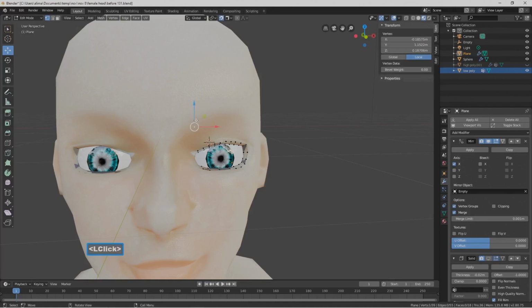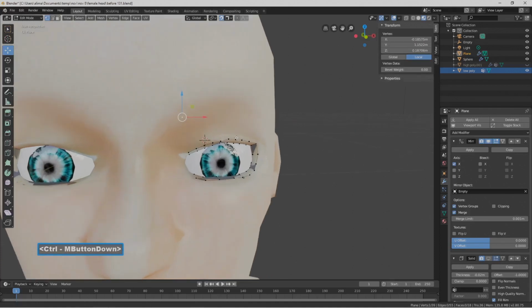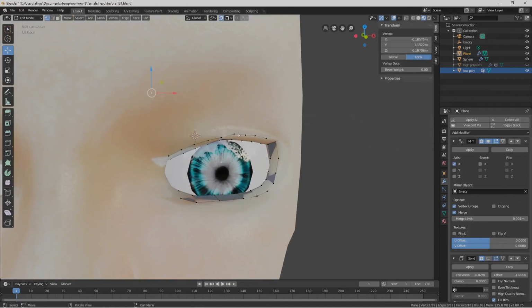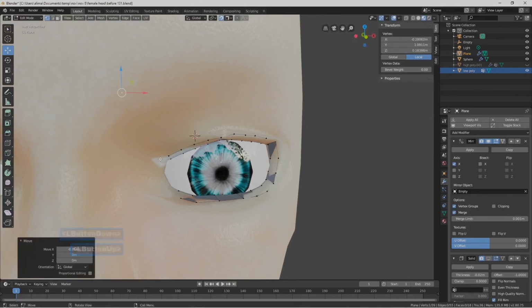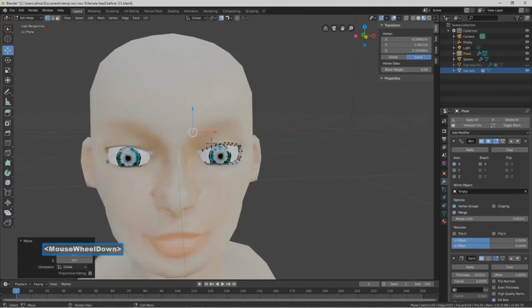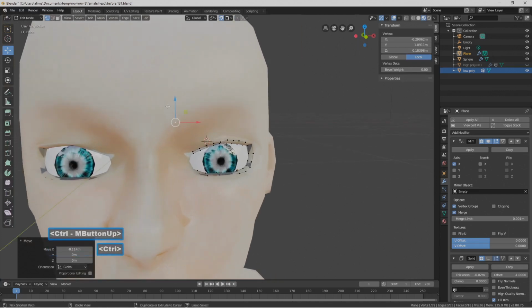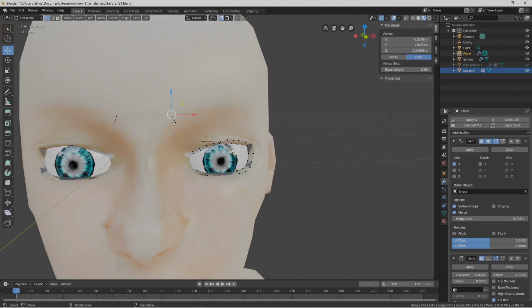Okay, the reason why we have this vertex here is we're going to do something similar to what we did here. Let's push this over. Here's the eye. We're pushing it a little past the eye towards the nose. Right on this bend is where we want it. I'm going to hold control as well as my mouse button to zoom in. I'm holding control. I'm going to right click. So when I right clicked, I extruded this geometry.